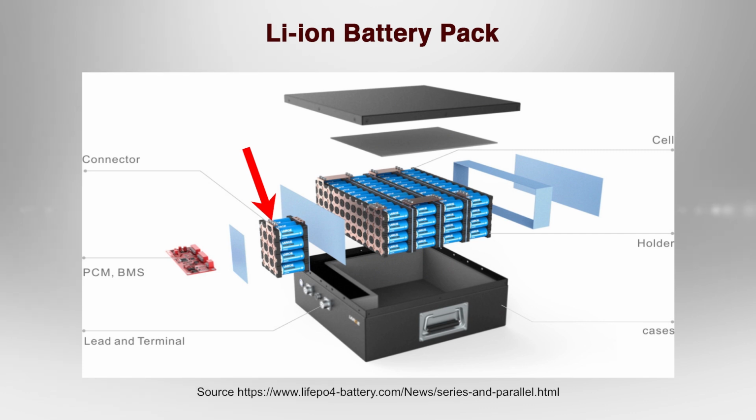So depending upon the customer requirement and application, the size and the capacity of the battery packs can be made. And no doubt for the telecom application it is used in a rack. So an individual rack can have multiple battery packs, and whenever we require high voltage operation, we will connect different battery packs in a series manner to get the high voltage.